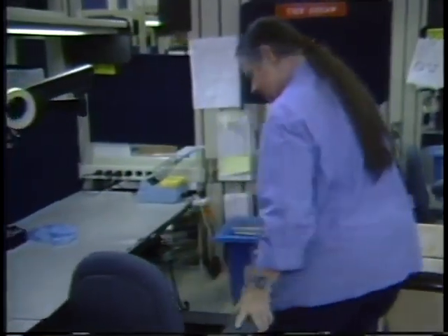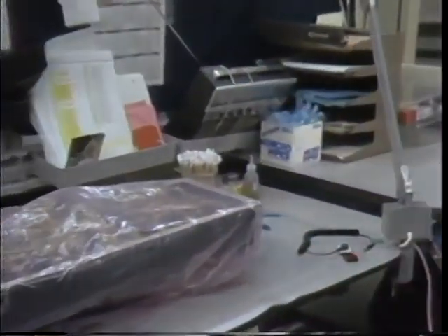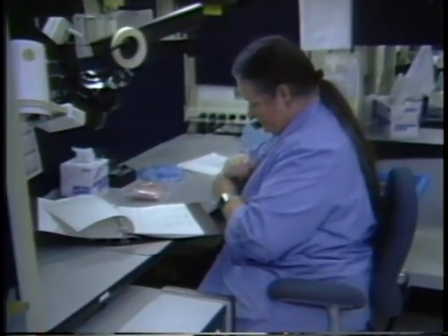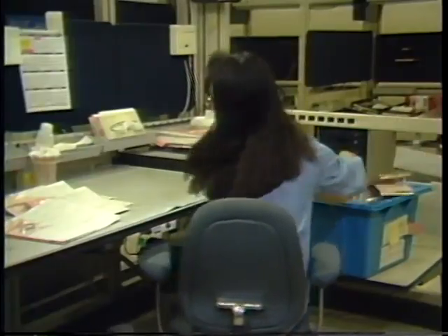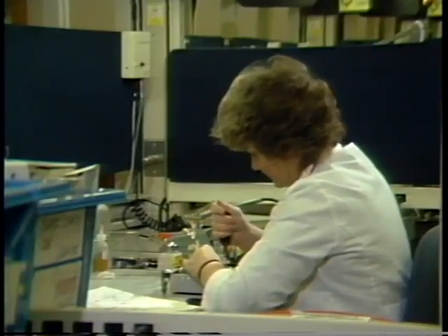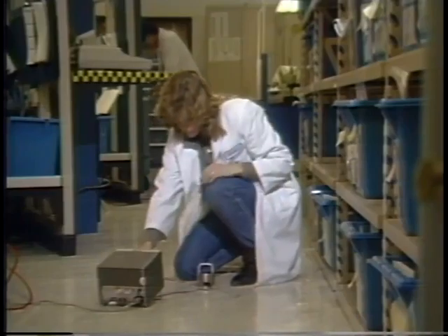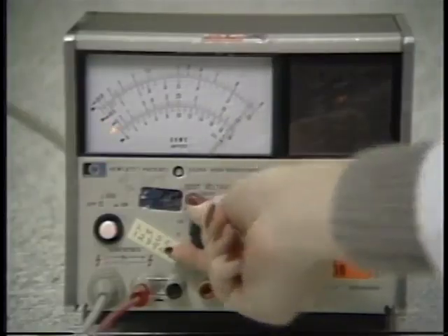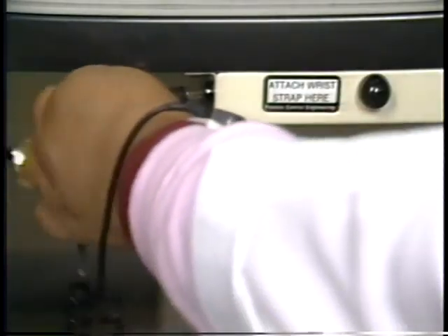To control ESD, you've got to have a static-controlled work area. All ESD work areas should be equipped with special work surfaces, wrist straps, and an identified wrist strap ground point. These areas are certified as ESD safe to help the operator maintain an ESD controlled area. ESD control workstation monitors are another aid for operators to verify that they are following correct procedures. Along with your workstation, floors, ovens, and other equipment are checked to provide ESD control. The controls I just described should already be built into your work areas.